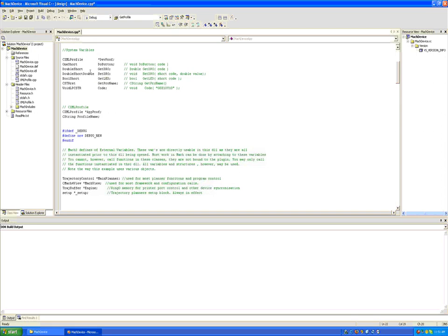Devprof is used to get access to the XML file in Mach3. It is a restricted pointer. You can only use it during two areas of this DLL while it is running. One is during the configuration, and the other is when the profile name is actually set. We'll go over that in a moment.